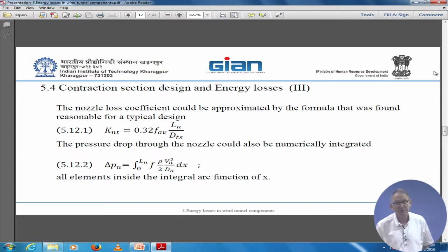It is not so critical, since the really effective elements for attenuating the turbulence level are the meshes and the screens. They are more effective. So this thing is not so dramatic. You just prefer to have it there to make sure that big fluid structures will not sweep down to your test section.